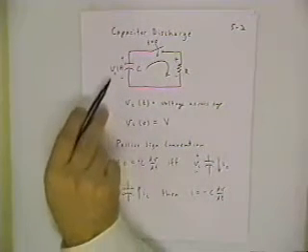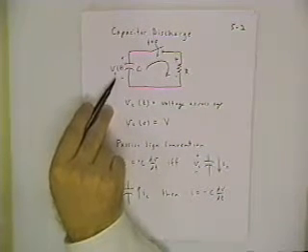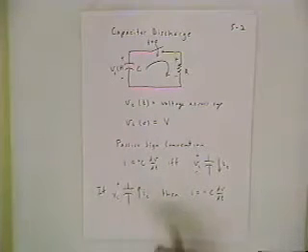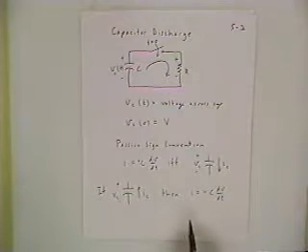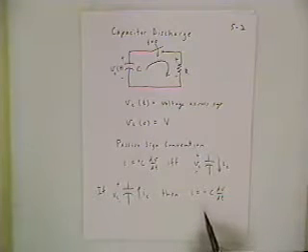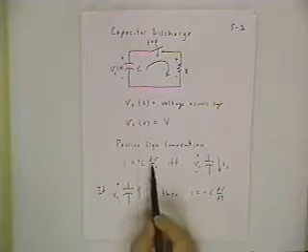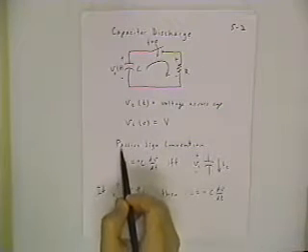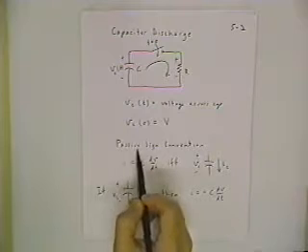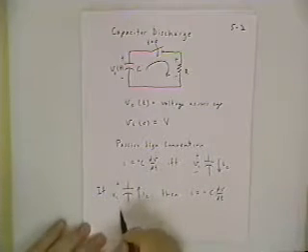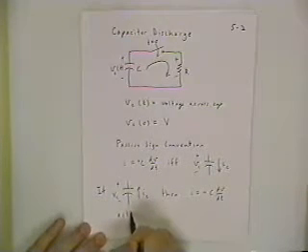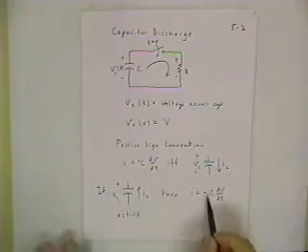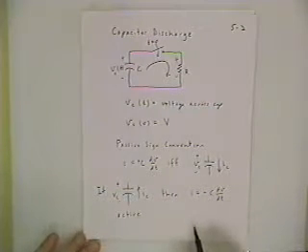The capacitor is acting temporarily, in this case, as a source of energy. And therefore, we need to have our power expression, P is equal to VI, match up correctly with the right algebraic sign. So that's where this name comes from. It's a positive sign in the linear model if the capacitor is acting like a passive element. But in this case, it's acting more like an active element. It's delivering energy to the rest of the circuit, and therefore you need a minus sign in the model.